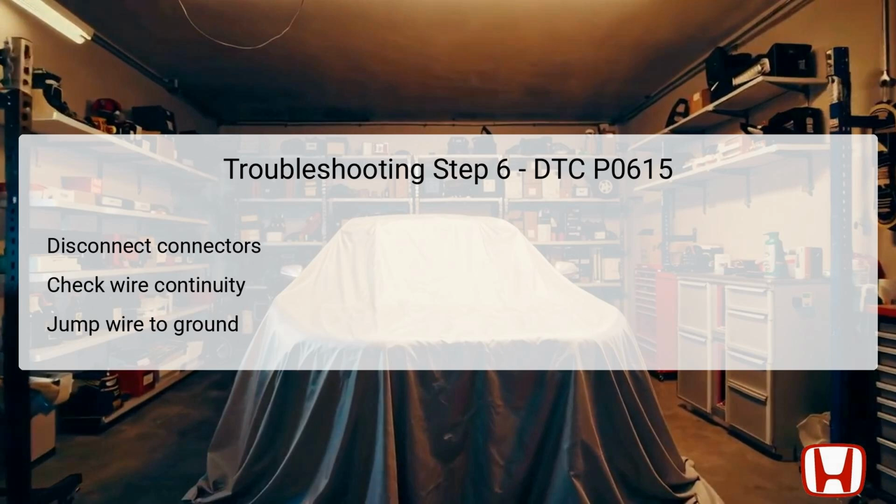Ensure the vehicle remains in the off-lock mode while verifying continuity between the specified test points. A positive continuity result indicates the integrity of the circuit, while a lack of continuity requires further inspection and repair of the IG1 ACG wire leading to the relay circuit board.